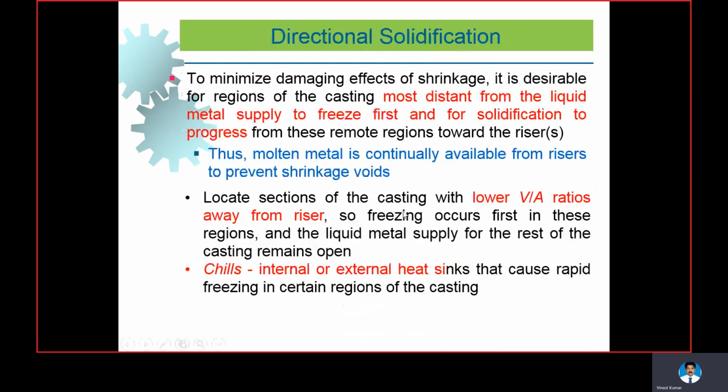So locate the sections of the casting with lower volume to area ratios. As I explained before, a lower volume to area ratio will get solidified quickly, so it should be away from the riser. So these are some concepts related to directional solidification.